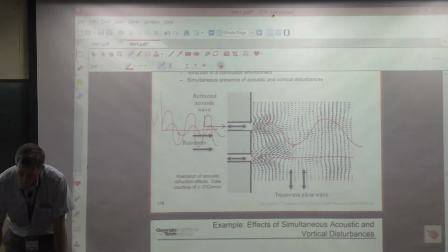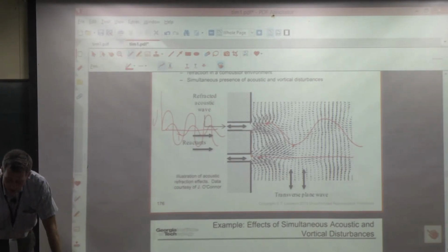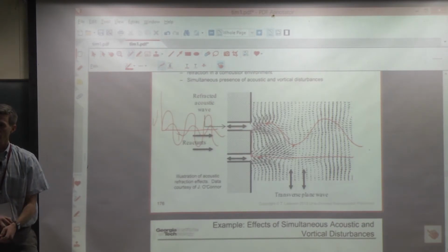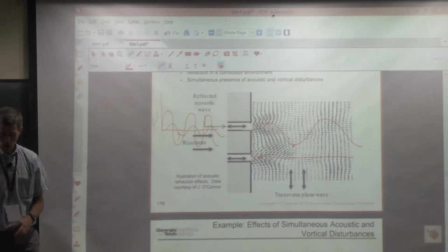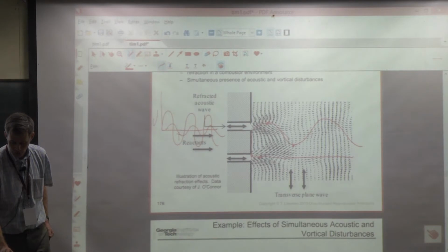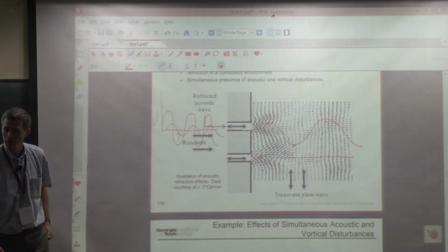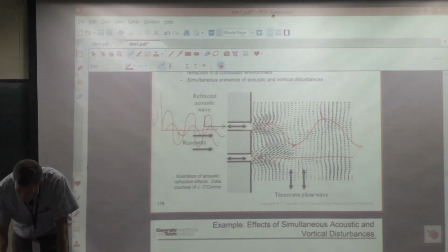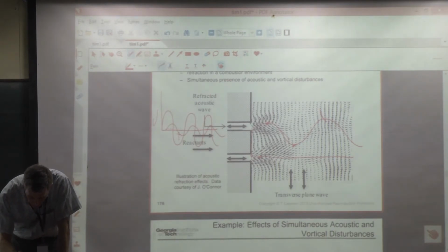Okay? So in other words, just to make sure, this plot here is not the instantaneous velocity, it's the magnitude of the velocity. So this is a harmonically forced system. The velocity is oscillating up and down harmonically with an amplitude given by this curve. And so what this is showing you is that, wow, the velocity is oscillating a whole lot more here than it is there, but then it's also oscillating more here. So what's going on? So in other words, if I were to then plot this point on this graph, again, there'd be a phase shift, but it would have a similar amplitude as the other one, so it might look something like this.